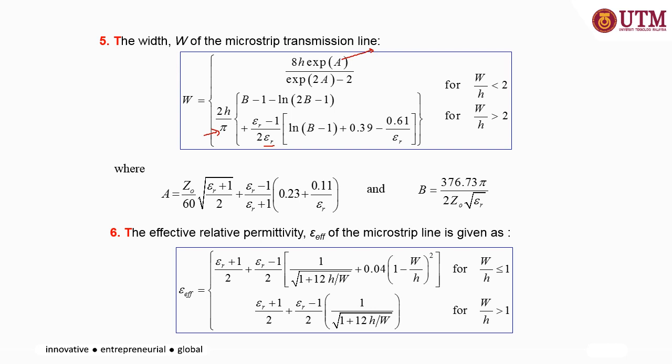So each of these can be determined by the following equations, and the effective permittivity of the microstrip line, due to the different permittivity involved in the signal transmission, can be simplified by using this equation. So basically the calculation has been made simpler by using a calculator. Okay, there's an online calculator which you can use to calculate the dimension of the microstrip line, prior to the design.